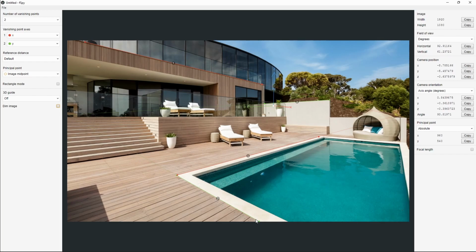Well, chances are that the image hasn't been manipulated. It is the desired situation, because in such a case, the principal point will be at the center. And because this is also the default value in fSpy, we don't have to do anything else. All 3 axes will have this nice alignment. This is the simple case, of course.